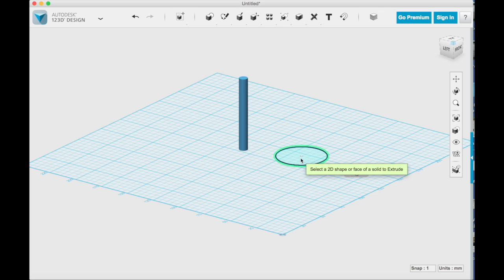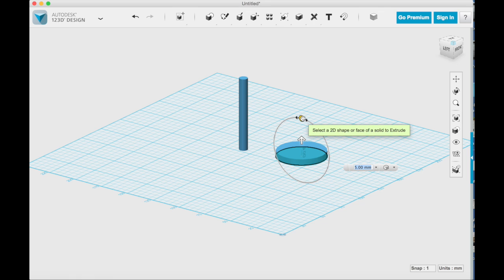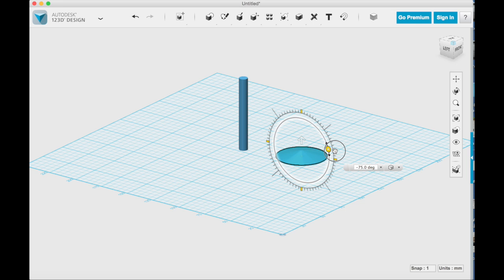When you click on it and you click the extrusion button, the extrusion menu item, then you could pull using the arrow, or you can add right in the dialog box there. You can put in the actual height of it. And if you see here, what you can also do is cause a taper. You'll see the rotation tool develop there.